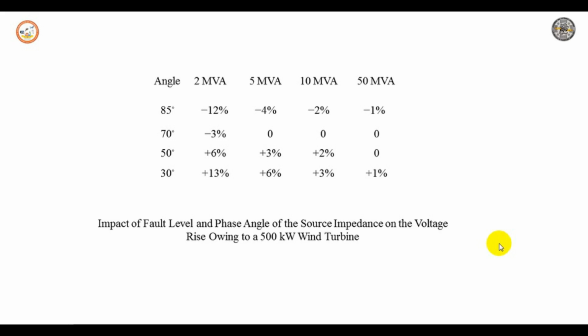The over voltage limit at 110% would set a hosting capacity of up to 30% for homes, which is still a significant amount of penetration that we used to achieve on the same network. This was used to study micro CHP in combination with solar power, looking only at the impact on average voltage.